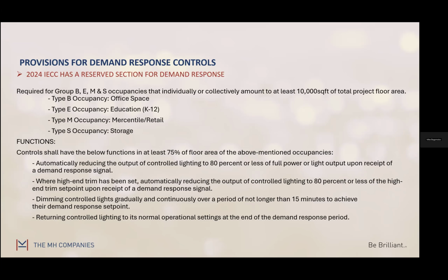But again, a lot of systems out there, I don't think are ready quite yet to really process this information. Most systems on the market are designed to do a last-signal-wins scenario, right? So if someone turned the lights off, and the next signal is the schedule that says sweep the lights off, it's going to follow that schedule. It's going to follow that next signal.